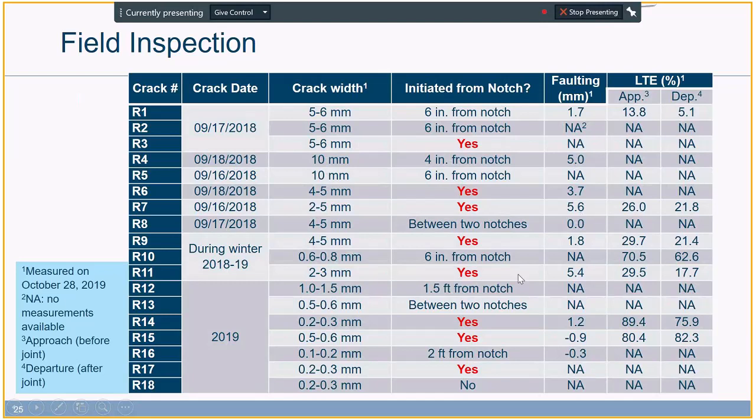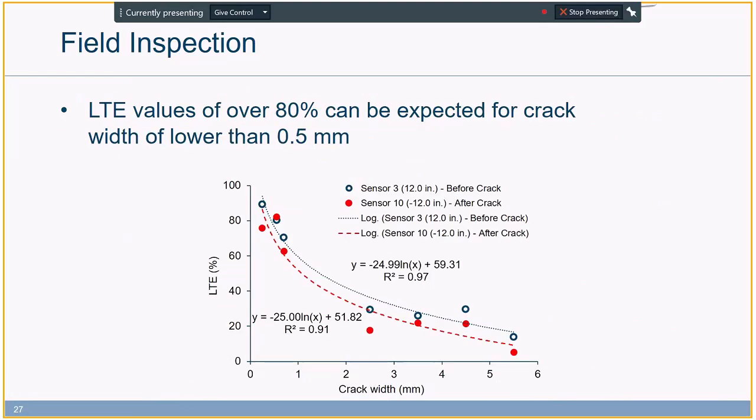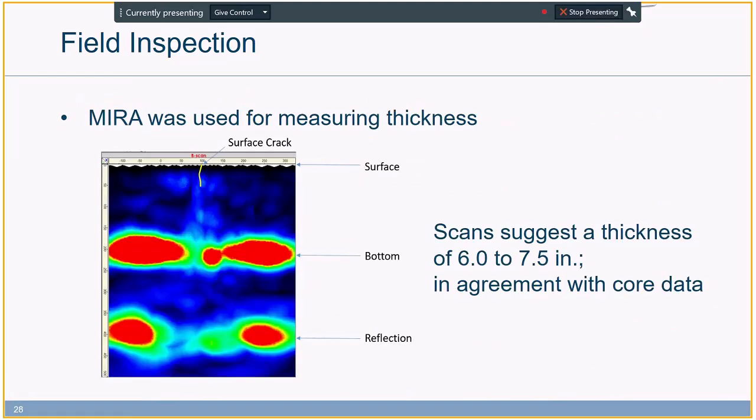Maybe it could be even worse if we didn't have the fibers, but I would say it's a good experience so far to learn how the performance is going to be. Is this the complete design? I would say no, but this is something that will definitely need more investigation, maybe some modeling and some more experimental work. Maybe a combination of fibers and dowel bars and joints, or as Bernard mentioned, maybe to have the notches from inside the ring as well. These are all scenarios that could be investigated.